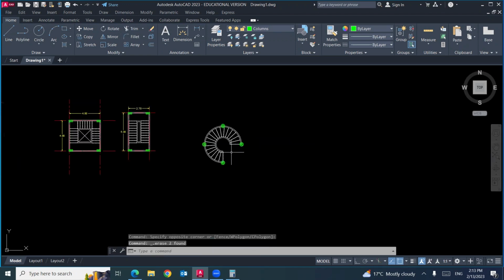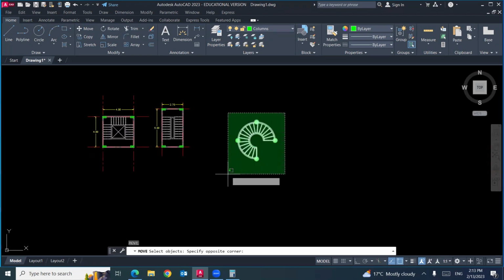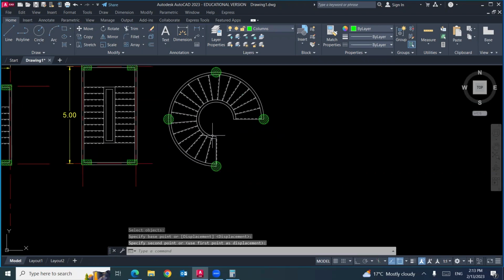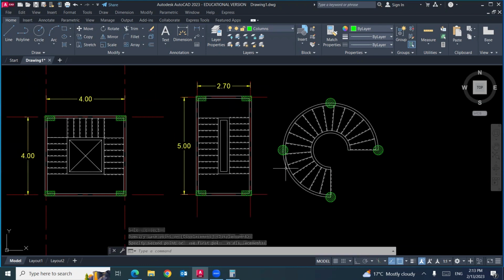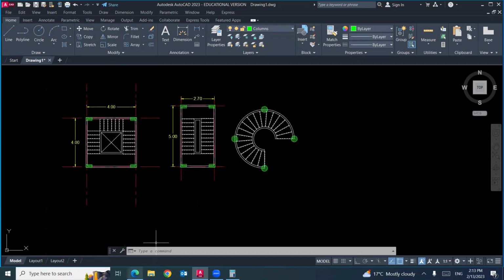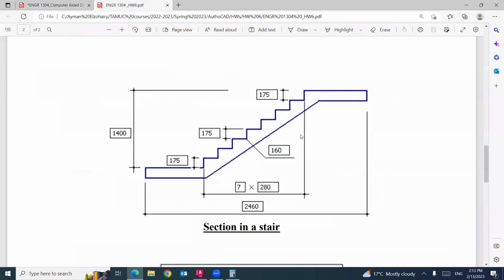Anyway, so these are the three different types of stairs, which is called 3 flights, 2 flights, and array. Keep in your mind, we are using offset all the time, trim, dashed line. We are using Boolean array for the helical stairs. The next one I will use is cross section of your stairs.